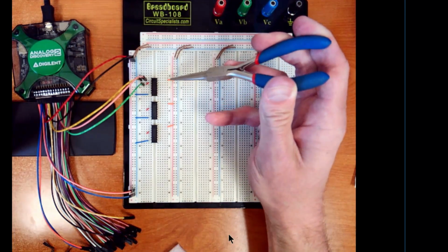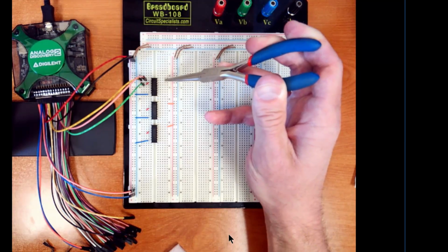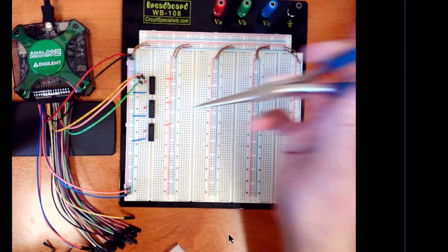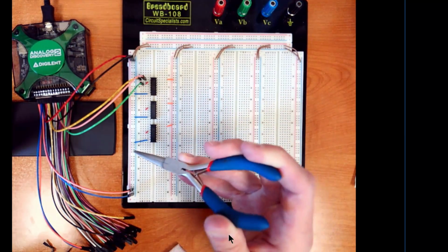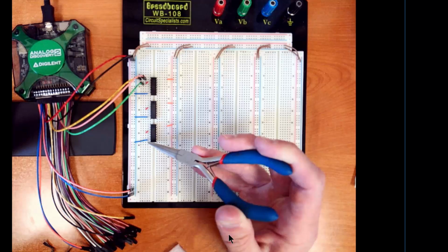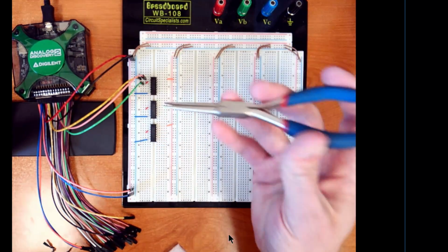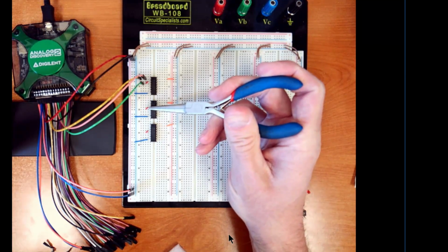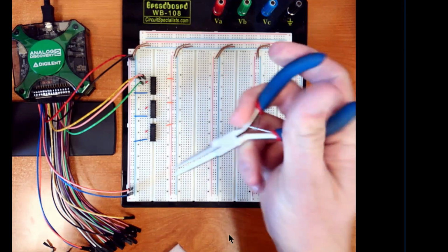Then I can just take a little jumper wire and go from the red over here on this strip into that strip, and I've got power now over there. And then I can do the same for the AND gate and the OR gate. And then to get ground, I simply use another wire and come down here to pin 7 on each of these devices, and I jumper that over into the ground strip. These little red wires are how I connect the output of the gate to the input of the next gate down, so you can just use those little guys.